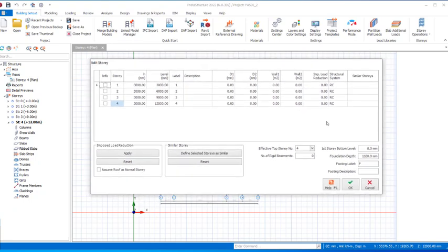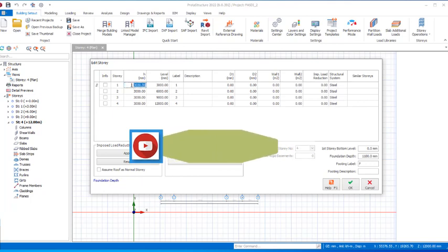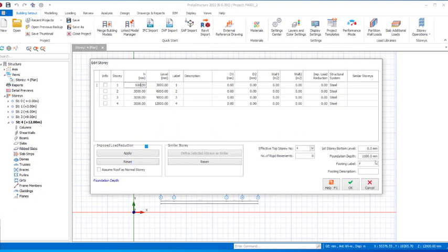So let's make progress. For the structural system, we will have to change it to steel, because steel will actually dominate the whole of the structure. So you change the structural system to steel successfully, just like this. After which we want to set the stories. We want the stories to be in 3 meters, but for the story 1, we will be changing it to 600. So this story 1 is just like from the normal ground level to the DPC level. It's going to be 600. For the foundation depth 1.1, we are okay with that for now. Click on the OK options.